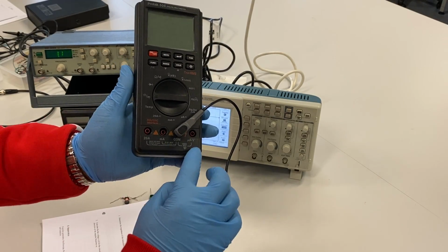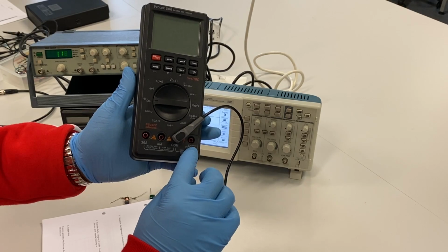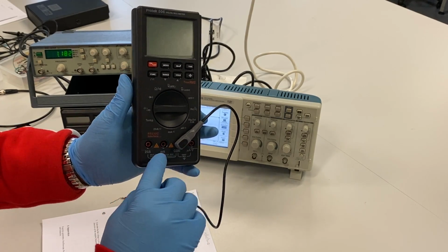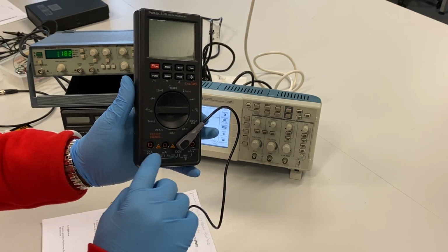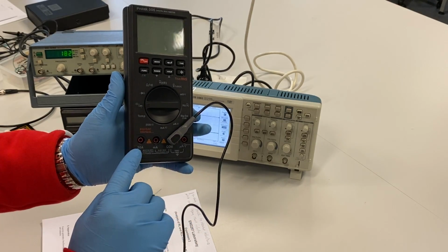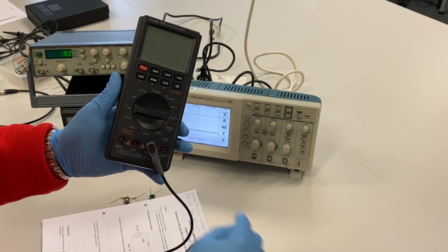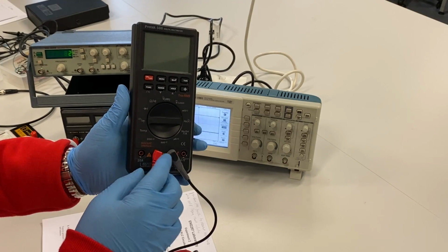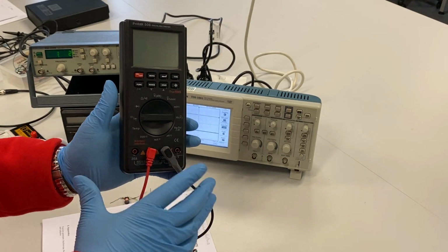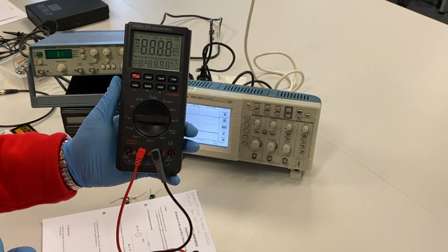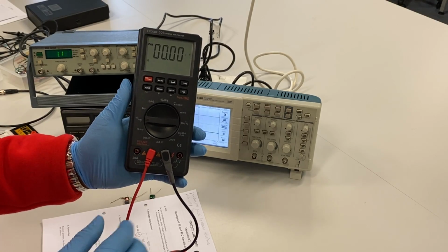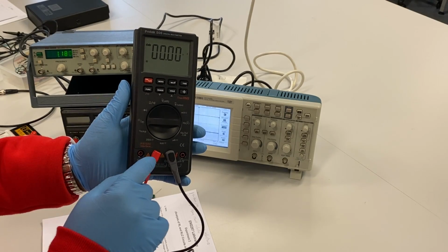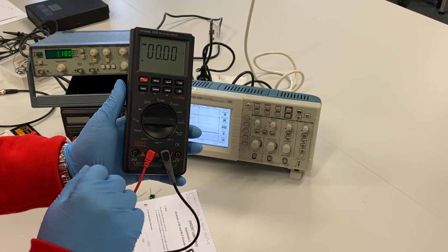There's COM, there's micro A dot V, this is voltage. Then there's milli A, this side is for current, with milli A and 20A. This is for the current side, this is the voltage side. So if you want to measure current, normally we work with milliamps in here or even microamps. So for us not to confuse the scale, what we normally do is we work in milliamps.